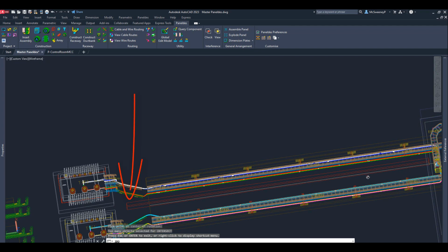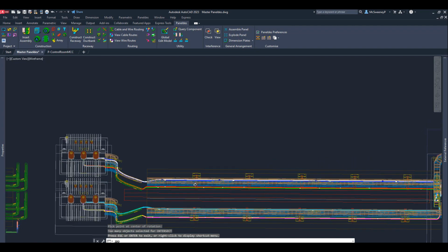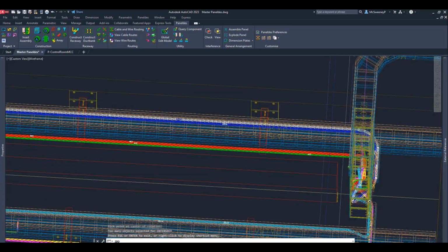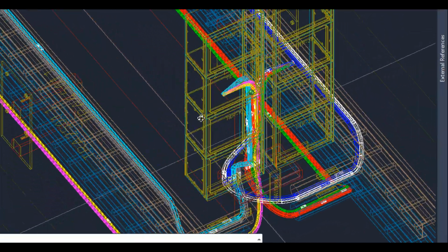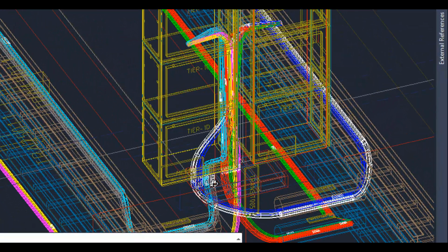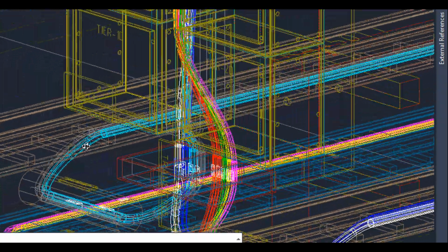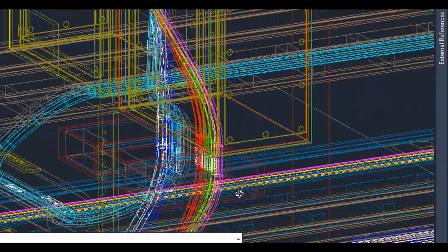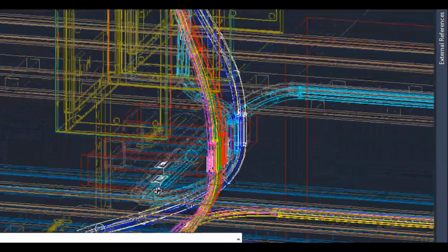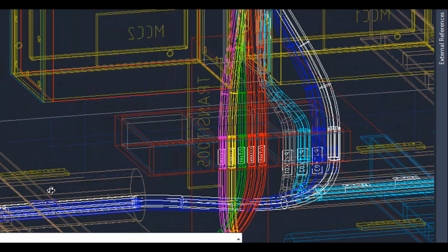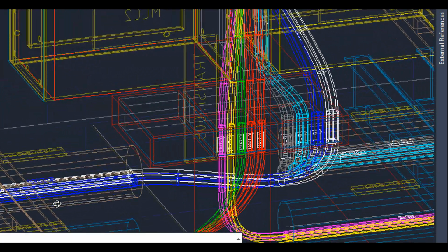Another feature of Paneldes Raceway is the smart transit system. Transits can be modelled and the routing system will route through them. Paneldes Raceway knows how to optimally fill the transits and how to select and quantify appropriate filling blocks. You can see a 3-frame Roxtec transit under my distribution panels. The transformer cables are routed through this transit. Transit frames are power level sensitive. You can mix or segregate your instrumentation cables from your LV cables by frame, etc.